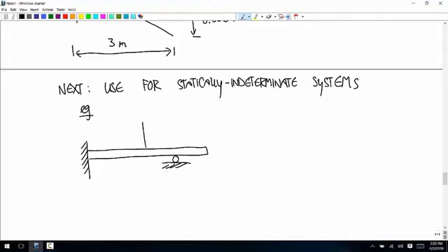And then you add your loads. Well, you can't do this as a statics problem because you only get 3 equations for this, and we have 3 variables for the load here and another variable there. So 3 equations, 4 variables. We couldn't solve that.